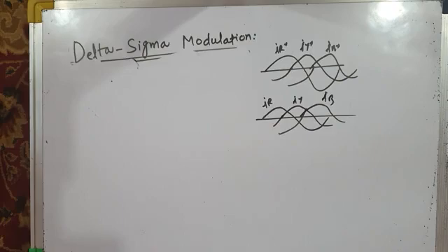So therefore, using bang-bang control or hysteresis current control, we are basically controlling the load current, the induction motor winding current. And indirectly, we are controlling the voltage of the inverter also. Because if you check the voltage of the inverter, the pole voltage, the line voltages, or the phase voltages, you will find that their instantaneous average values are sinusoidally varying. So you are indirectly controlling the voltage. What you are directly controlling is the load current. That's why these types of inverters are also called current controlled PWM voltage source inverters. By using the bang-bang control or hysteresis current control, we are directly controlling the current.